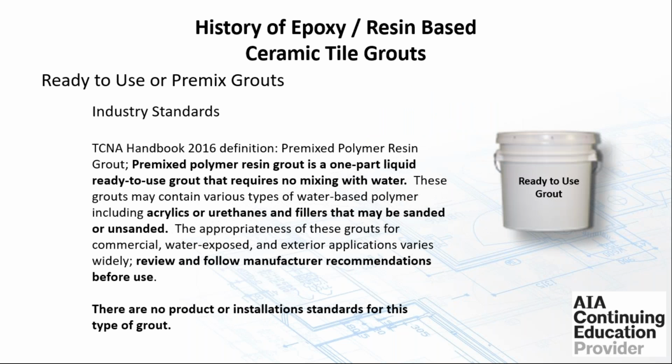Now we start taking a look at the ready-to-use grouts. Excuse me, not the epoxy grouts, the ready-to-use grouts. Jumped ahead of myself. This is something relatively new on the market in the last couple of years, to where rather than going in and mixing up a cement grout with water, you go into the job, bring out the bucket, open the bucket, and the product is ready to use. There's no mixing involved. You take it out and you start spreading it like you would a mixed cement grout.